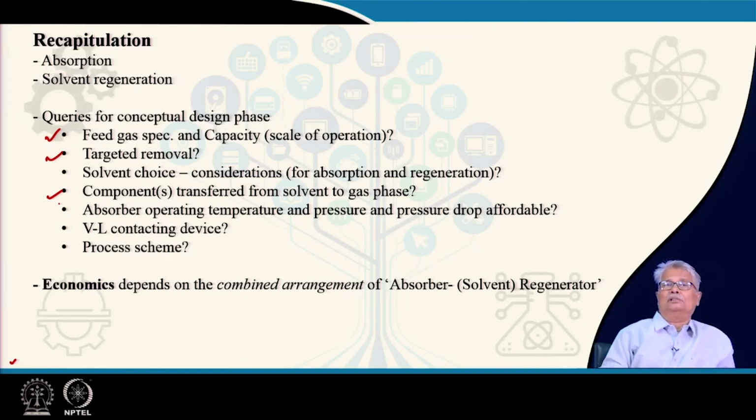It is important to note one thing, that is the absorber operating temperature. Normally, the absorption process is associated with liberation of a small heat of absorption. So, based on the fundamental thermodynamics, absorbers work better at lower temperatures.